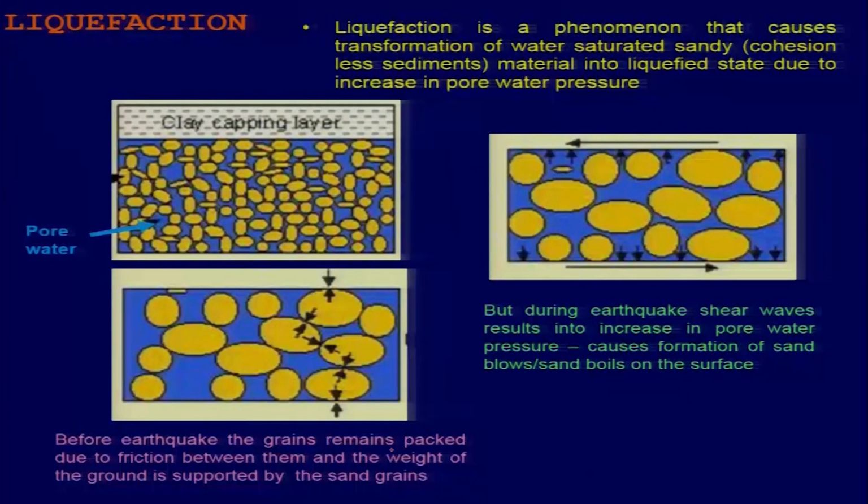So liquefaction is defined as a phenomenon that causes transformation of water saturated sandy or silty, or you can say cohesionless sediments. It transforms the material into a liquefied state due to increase in pore water pressure. And since the pressure is low towards the surface, the high pore water with higher pressure will break the surface and come out of the surface.